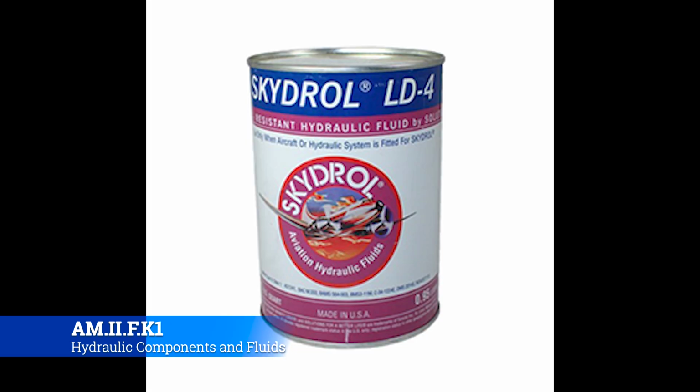Okay, and finally, phosphate ester-based fluid, or commonly referred to as Skydrol in heavy commercial aviation. This is the most common hydraulic fluid that you will come across if you end up working on heavy metal aircraft. I will tell you, it will burn your skin, it will burn your eyes. You don't want to get this stuff on you if you can help it. But a lot of times, especially if you're working in the wheel well of a 737, this stuff is everywhere, and it's going to get on you.